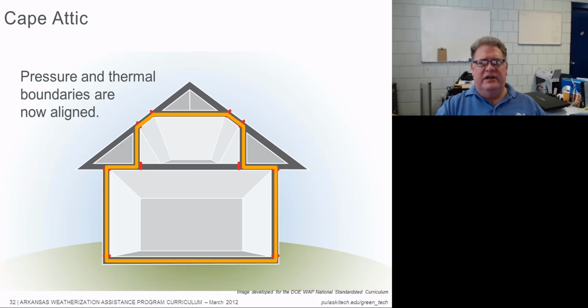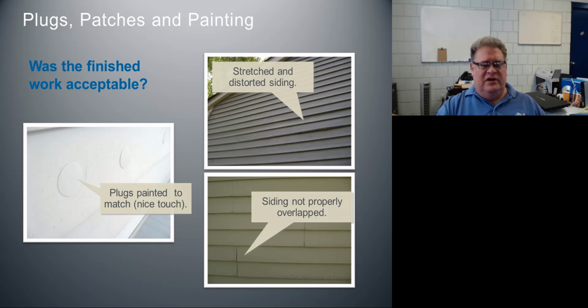The other thing is we need to make sure that the attic up there has been properly treated. These are areas inspectors don't like to get into because they're always tight, but we need to get into them and make sure that our crews are doing a really good job in there, especially here in the south, where knee walls tend to have the highest delta T in the house. We can see a 70-degree delta T across that wall, and that is a huge driver or motivator for heat to move. We don't want to lose a bunch of heat through that.